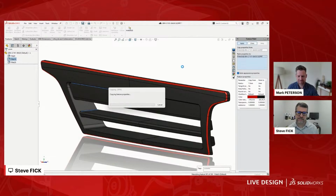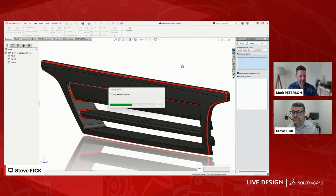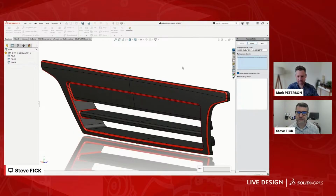And the nice thing about this is, I don't have to go into every feature and choose edit feature. Once I load them up, it just takes care of adding that. I will say this, you need to do like features. So for instance, I can't take an extruded cut and copy a hole wizard hole to it. So the features need to map and need to be of the same kind for this to work. But again, a feature maybe not a lot of people will know about, and it's pretty handy.